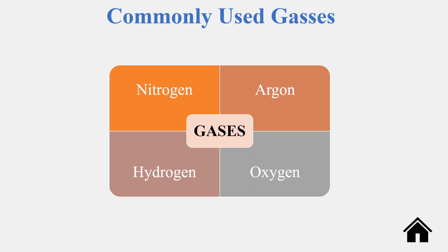And we can even use a blend and combination of these gases depending upon the requirement. Sometimes water is also used, basically to remove the metal pieces and debris that are left when the plasma cuts the metal, for the purpose of cleaning. And this is all about commonly used gases in plasma.